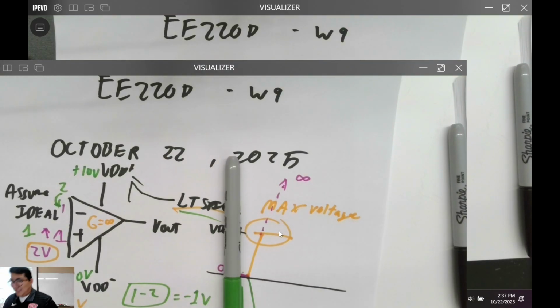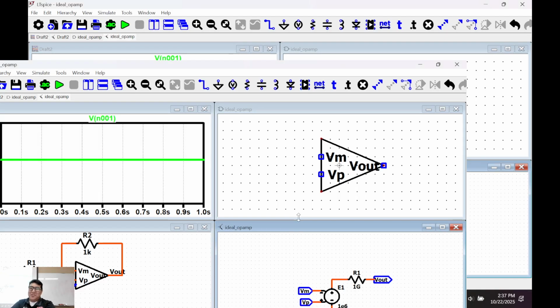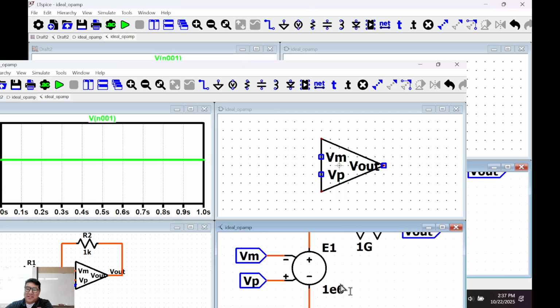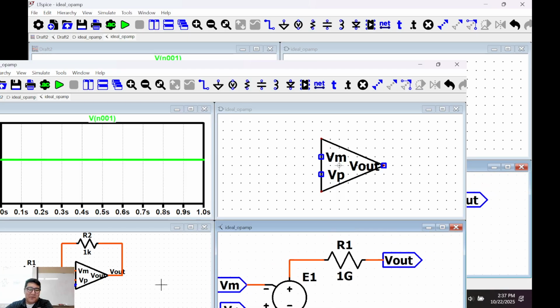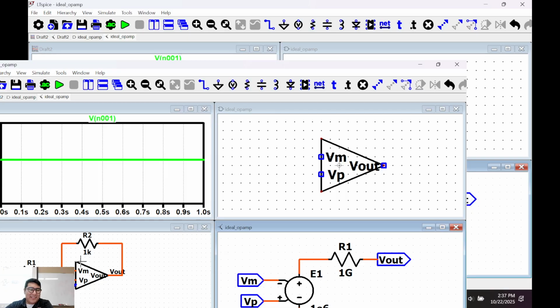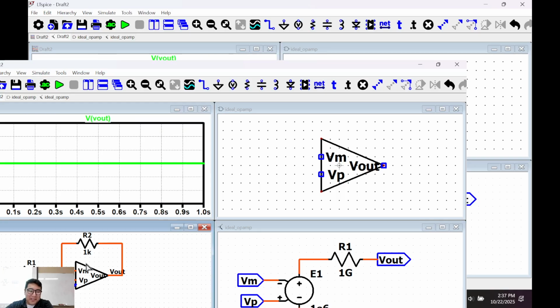So yeah, and then I guess I'll show everyone what they were missing during our little introduction. What I was trying to do was create this ideal model where I got this right here. This right here is a voltage controlled voltage source. Got this. I put a resistor here, but tried it and it didn't work as well as I wanted. It just acted like a normal voltage divider, treating this as 0. Not so sure why that's the case, unless the output resistance needs to be infinity, but there's no way.